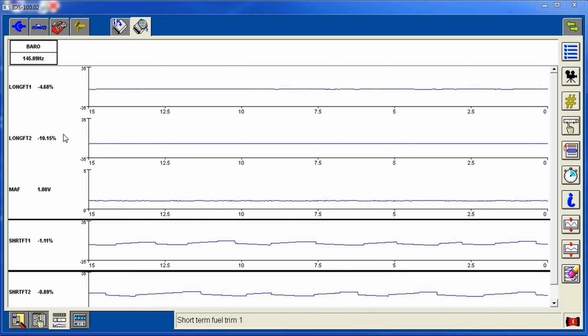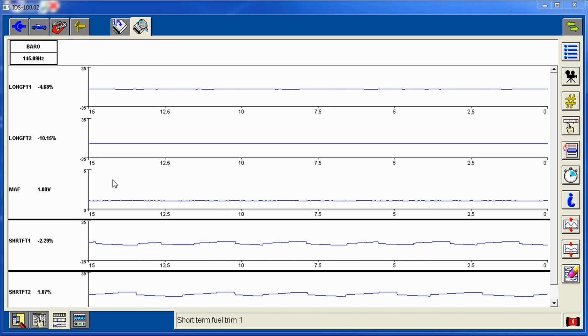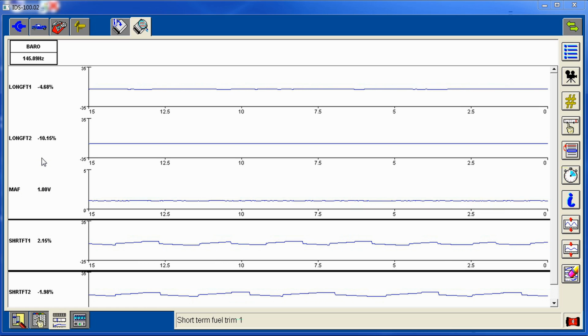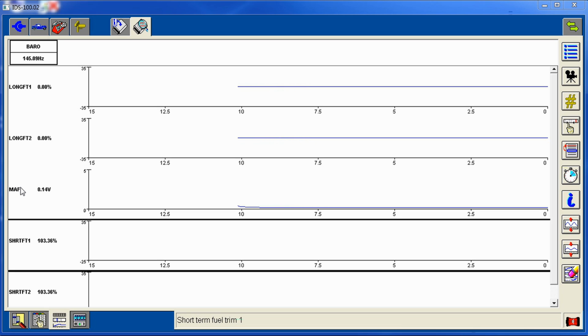Okay, so here is the truck at idle, hot idle, with the old mass airflow sensor in here. Now you can see it's like 0.9 or so. You have the AC on, so it's a little bit higher RPM, so our mass airflow readings will be a little bit high. But look at this. Key off, key back on. No airflow, right? Turn the AC back off. Look right here. We have a mass airflow reading of 0.150 pretty much, 140 millivolts, and there's no air flowing through there. So already our mass airflow sensor reading is skewed.